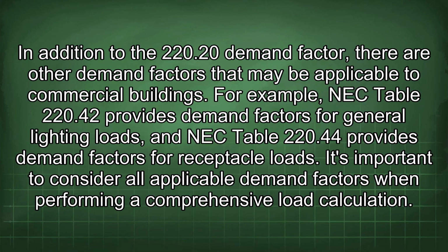For example, NEC Table 220.42 provides demand factors for general lighting loads, and NEC Table 220.44 provides demand factors for receptacle loads. It's important to consider all applicable demand factors when performing a comprehensive load calculation.